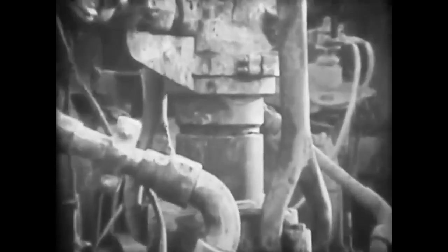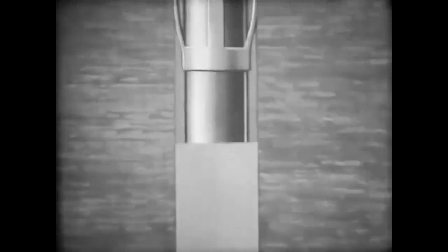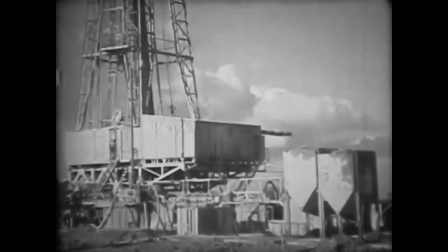The cement is a wet slurry, pumped down the inside of the casing under pressure. Downhole, it flows through the end of the casing and is circulated around the outside and back to the surface, displacing the drilling mud ahead of it. The cement is followed by drilling mud to the bottom of the casing. The pumps are stopped, and the cement is given time to set.